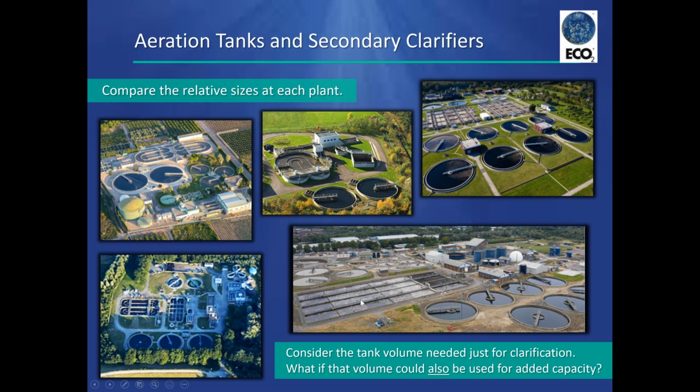So we have to transfer a certain number of pounds of oxygen per day to meet the demand for the bacteria to aerobically remove the pollutant. So you look at this aeration tank, and if you had a coarse bubble aeration tank, you would be putting in 100 cubic feet of air and dissolving only 1 cubic foot of oxygen. So you can see the turbulence there is quite high.